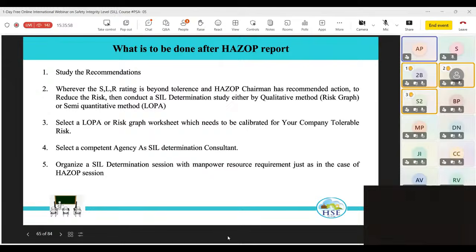What are the prerequisites? See, what question did the consultant ask? Do we have a record of how many times this group has failed? Okay. So the people tried to search that record and they did not find any specific answer to this. That's why it has to go to the next criticality assessment of the LSHS. Okay. So what you need for a LOPA session is,